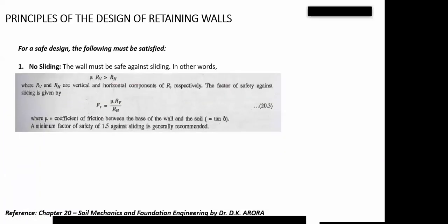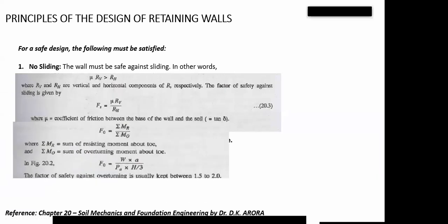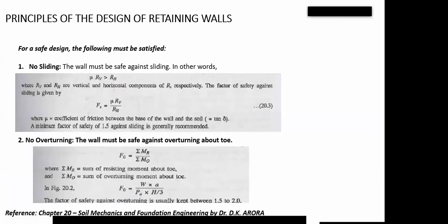And so, for us to prevent overturning, what basically causes overturning? From your knowledge of slope stability that Shemun taught, we have our overturning moments and we have our what? Our resisting moments. I need to emphatically tell you that one thing is only responsible for your overturning moment, and that's your horizontal forces. So, in a particular scenario whereby you only have your active earth pressure acting on it,